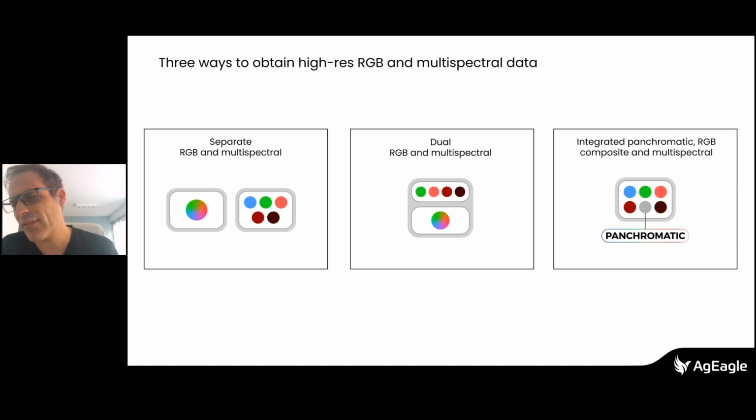It has a little bit of bad fame, the blue band, because historically, when we work with satellite imagery, we would say no, we're not going to work with the blue band because it has too much backscatter from the sky. The sky is blue because it gets reflected by the particles in the sky. So when it gets down to Earth, it's too contaminated. So we're not going to use that band. But when we work with drones, we can perfectly use the blue band. We can have it calibrated. We can have correct radiometric information for the blue band as well. So it's not a band that we should not use for analytics.